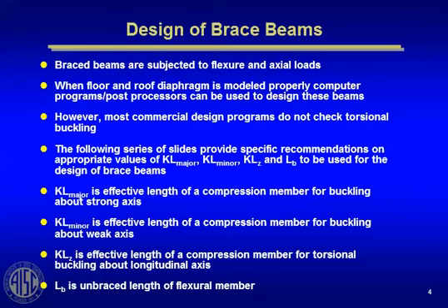Also, if you use a program like ETABS or any of them that have the rigid diaphragm capability, you have to be very careful that the rigid diaphragm assumption is inhibiting the axial deformation of this brace beam. Because if you connect it to the rigid diaphragm, and there's no deformation in a rigid diaphragm, therefore there would be no deformation in your brace beam, and you would be underestimating some of the drift caused by the shortening of this brace beam.